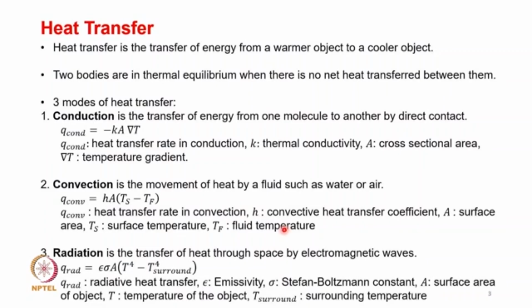Why? Because heat transfer is typically affected by fluid movement, so you need to take into consideration both the surface temperature where the heat transfer occurs and the fluid temperature that actually takes away the heat. So the heat transfer coefficient H and the area play a key role.